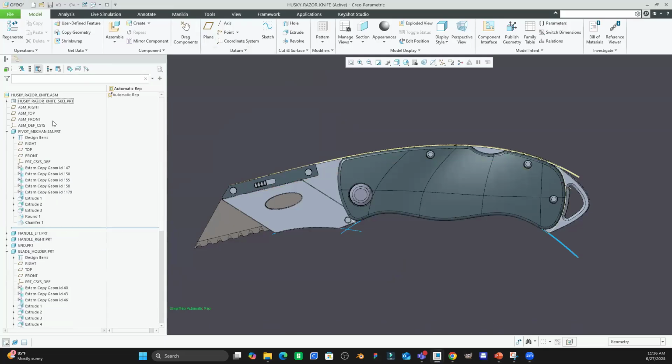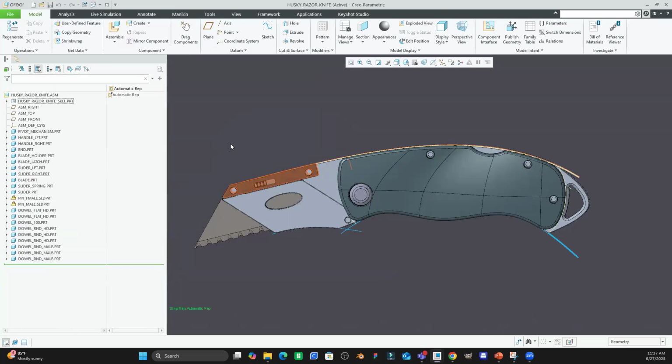What's cool now too is I'm not sure how many of you use it, but in Creo 7 they introduced the multi-body part functionality, and that's great. Other software had it before Creo, but it's a great way to merge bodies together, cut one body out of another, and find the intersection between them. You can also use a multi-body part for a top-down design where that part becomes a master model for an assembly. That's a whole other conversation that we can have later. But you can now create a shrink wrap of bodies.